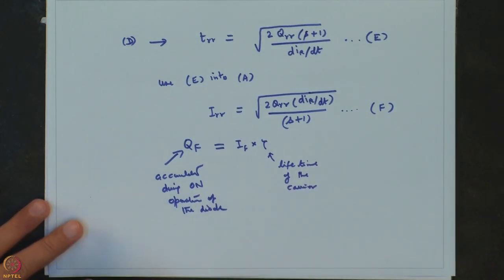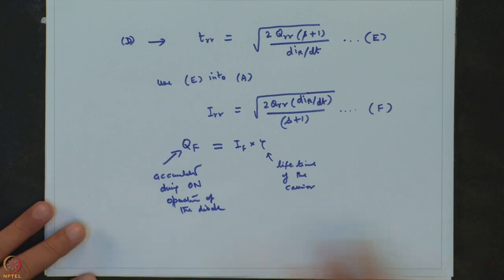So basically, when a carrier is in a certain region, how long can it survive before it recombines either with a hole or with an electron. If it is a hole, how long before it recombines with an electron, or if it is an electron, how long before it recombines with a hole. This average time is considered to be their lifetime, how much they can live in a particular region of a semiconductor. This is how it is defined as the most basic term.